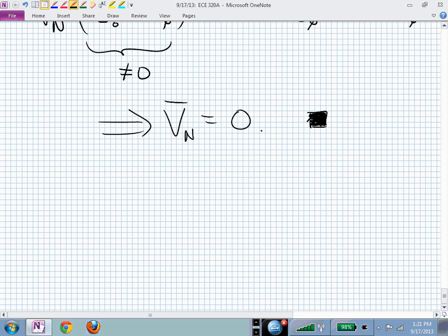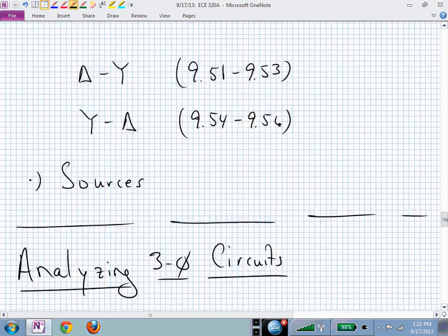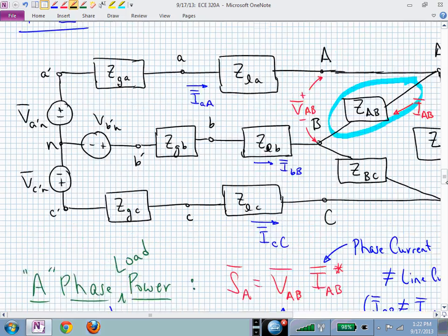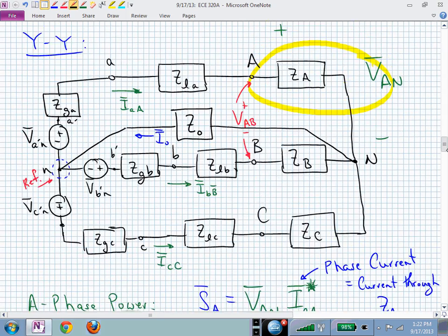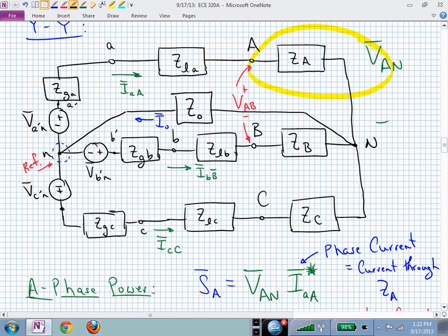But this now allows us to make a couple of different observations. What if we go back to our YY, now I have to find it. We assumed little n was zero, didn't we? As far as that was our reference voltage, that was zero. We've just demonstrated that capital N's terminal is also zero. That means we have 0 volts across that neutral conductor.